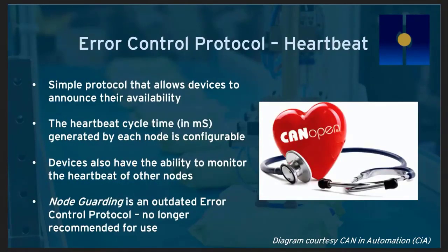Now let's talk about another useful protocol in CANopen, very similar actually to what we have in CSCAN. For those of you who attended our CSCAN session, you may remember that we talked about heartbeat messages. We have the ability in CSCAN from logic to send and receive heartbeats so that we can ensure that our device is healthy, and we can broadcast that fact to other devices that are paying attention to our data. It works almost exactly the same in CANopen.